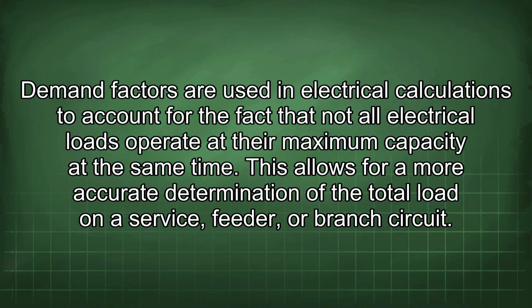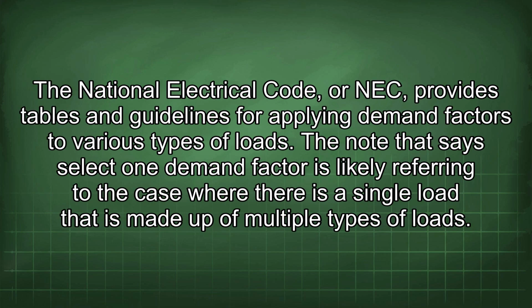Demand factors are used in electrical calculations to account for the fact that not all electrical loads operate at their maximum capacity at the same time. This allows for a more accurate determination of the total load on a service, feeder, or branch circuit. The National Electrical Code, or NEC, provides tables and guidelines for applying demand factors to various types of loads.